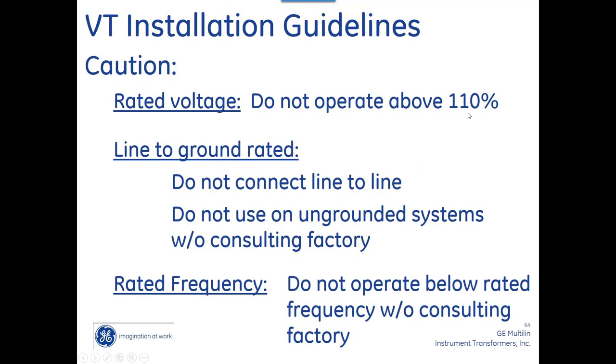VT installation. You don't want to operate a VT over 110%. You need to be careful whether it's line to ground rated or line to line. So let me ask you a question here. If I've got a PT that's got 2 bushings on it, is that rated for line to line or line to ground?